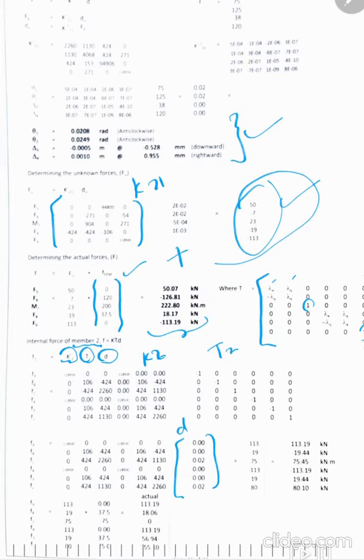After you calculate, you will get the values, and be careful with the units. Then sum these values with the fixed end moment values to get the actual forces.